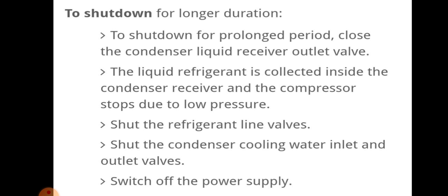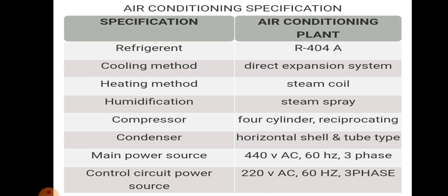Shut the refrigerant liquid valve. Shut the condenser cooling water inlet and outlet valve and switch off the power supply.